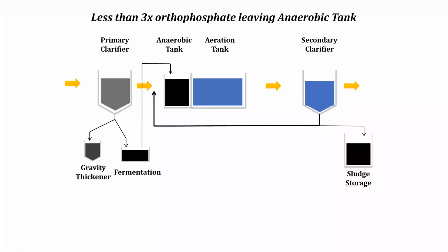All right, deep breath. So that was an attempt to sleuth out where the phosphorus removal was not performing to our satisfaction when this tank was working. Now we're going to say this tank is not working. It's getting less than 3 times. If it's getting more than 3 times, you got dead crud in there dying and releasing phosphorus. If it's less than 3 times, it's probably the conditions, either the ORP or the BOD is problematic.